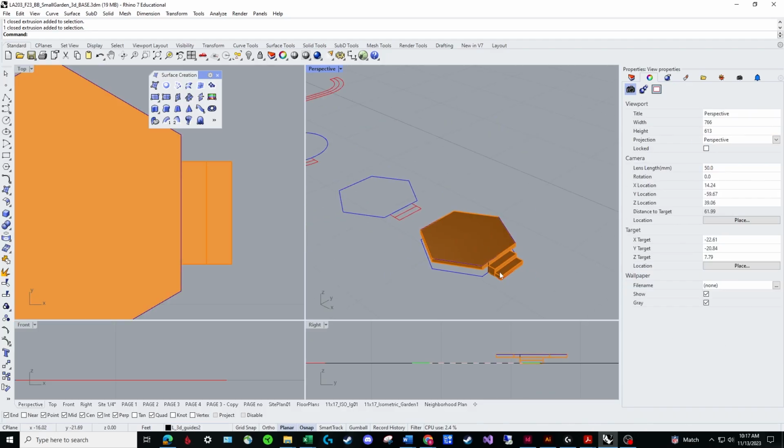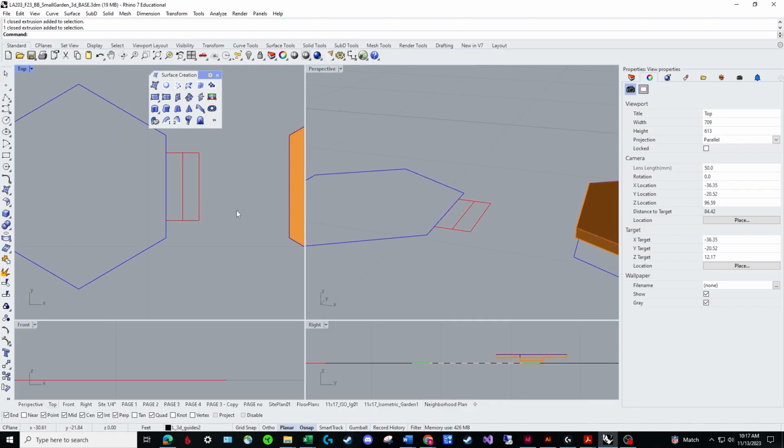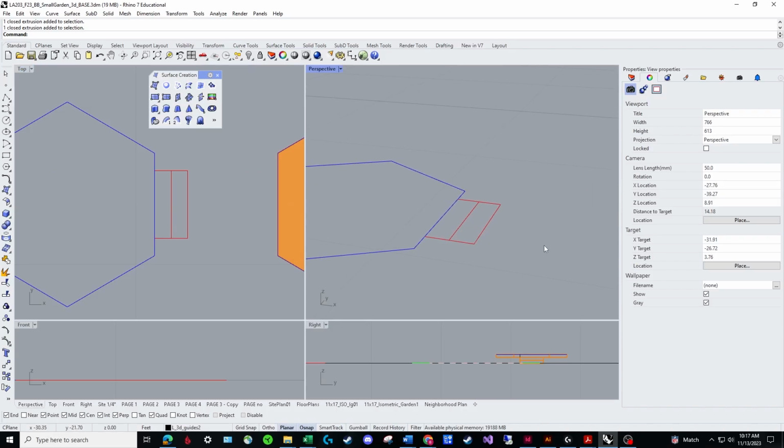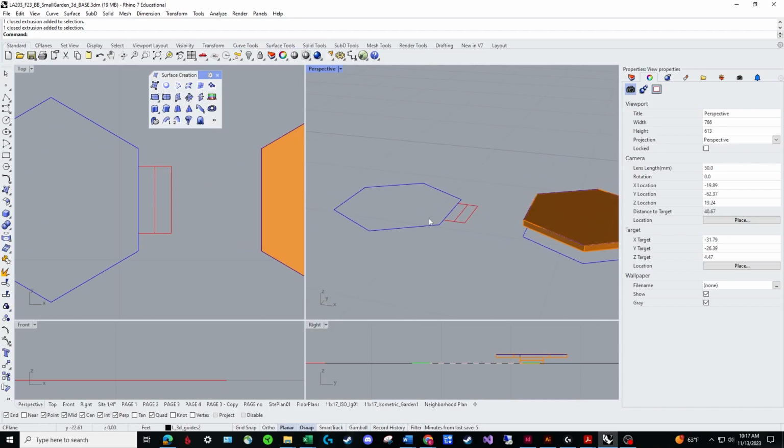So I went ahead and turned those onto their own layer, put them on the stairs layer, and there's that. So we'll do a similar one here, but in this case, we'll still use extrude, but one of the problems with this particular one is that you end up with this kind of line geometry, and you can imagine that if this were concrete, this would all be one unit, so it's kind of weird to have these as two different things. And if you ever had to edit, if you have 6 or 8 stairs, you'd end up having to basically erase this and do this again. It's somewhat easier, I think, to have it all as one unit. And so that's what we're going to do with this one.